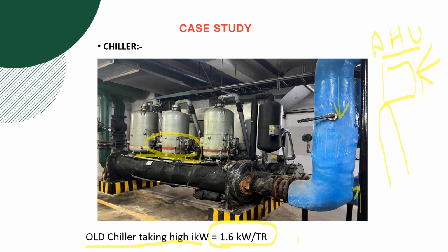Now I'll compare it with the ACs which we use in our households. For 1 TR, 1 ton refrigeration, or 1 ton AC, the energy used is approximately 1200 watt, or 1.2 kilowatt we can say, or it can be 1.5 kilowatt also for low star rated ACs.